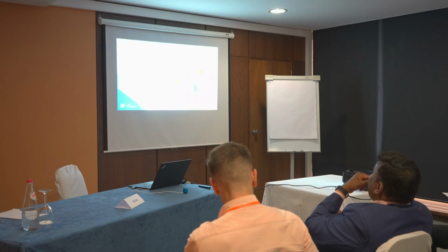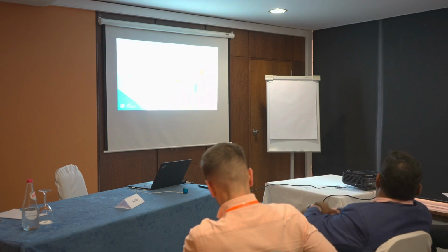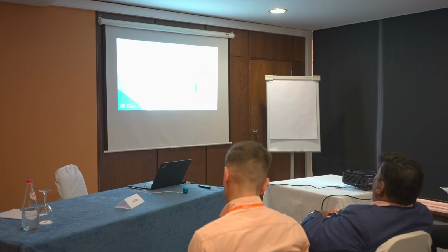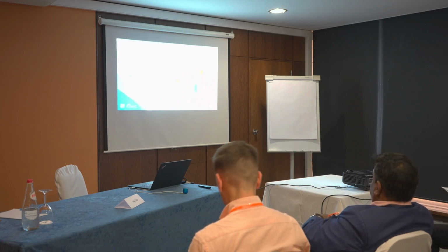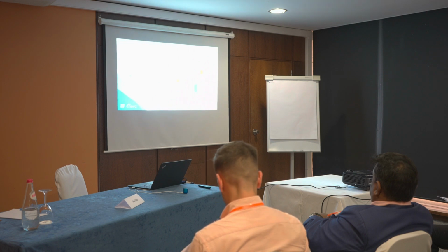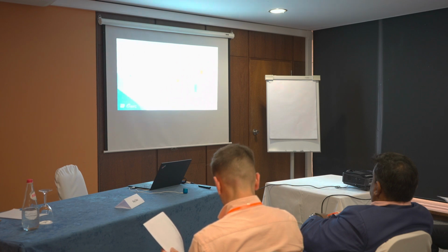Here we can see the different mechanical properties obtained beyond modulus, which is about 207 to 210 for the quasi-static testing. For the dynamic one, we have a range from 240 to 460 depending on the strain rate. The 0.2 proof strength is also increased, from 640 to 688 in the dynamic one, and about 480 to 500 in the quasi-static one.